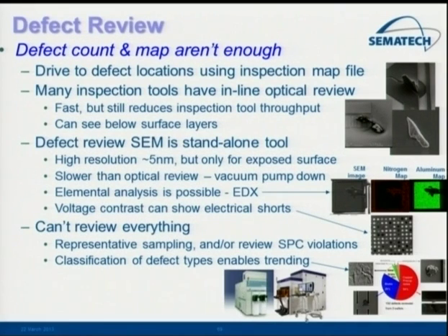Well, let's also take the signal from the X-rays, plot the one from aluminum, and you can start to see, well, this is an aluminum line. It looks like we have some sort of nitrogen-containing defect on top of it. In that case, it's my guess, it's not listed on here, but we use a lot of titanium nitride and tantalum nitride, or even silicon nitride films that could make up that. And so it gives you some idea of the composition of that defect.